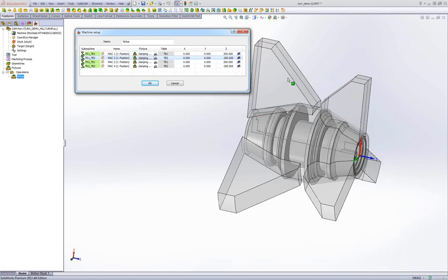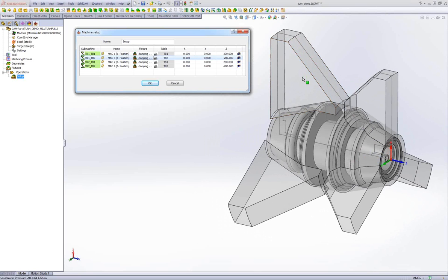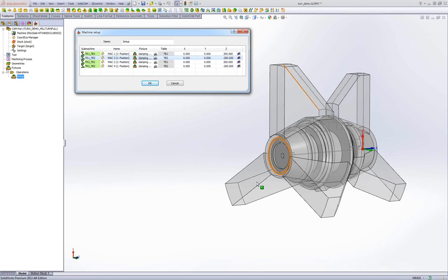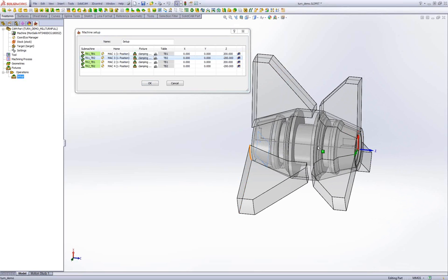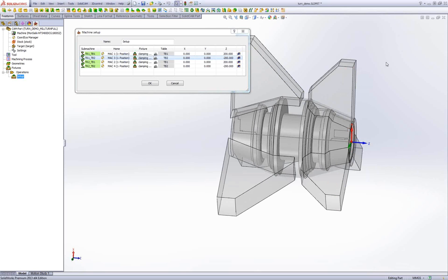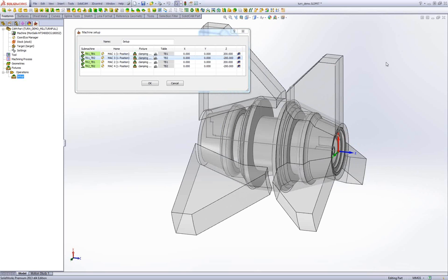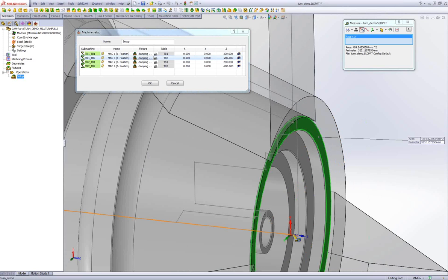Now, why did I unhide the 3D models, to select them and also to measure? Because I want this face of the jaw to be connected to the main spindle. I want this face of the back spindle fixture to be connected to the face of the back spindle. Now, I just need to measure the correct values from the face, because on this face we have the coordinate system.